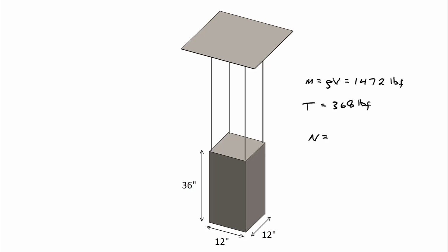Okay. So we're gonna use the yield stress in this case. I don't know what the yield stress of steel is. Yeah, exactly. We'll use the yield strength as our benchmark for defining failure. For common structural steel, the yield stress is typically around 36,000 psi, or pounds per square inch. So we'll take that yield strength and make sure that the stress in the rod under the factored load stays well below that. That's how we'll pick the diameter.